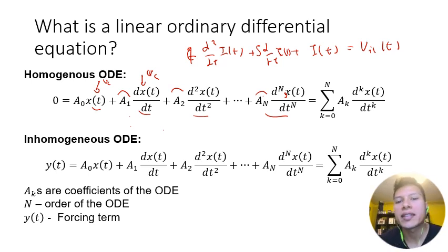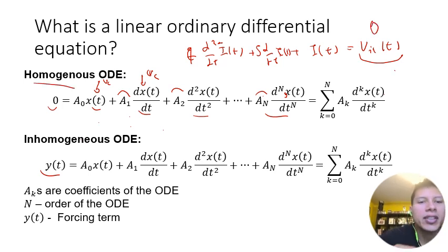This is what we would call a second order differential equation, because the highest order derivative that you can see is second order. Additionally, it's inhomogeneous because the right-hand side isn't 0. If the forcing term or the input voltage were set to 0, that's what we call homogeneous. If it's not 0, we call it inhomogeneous.